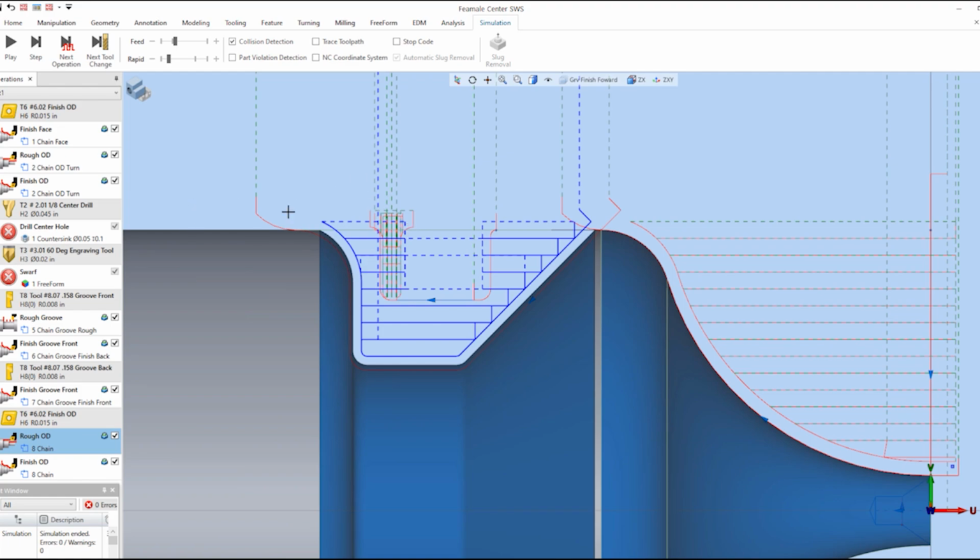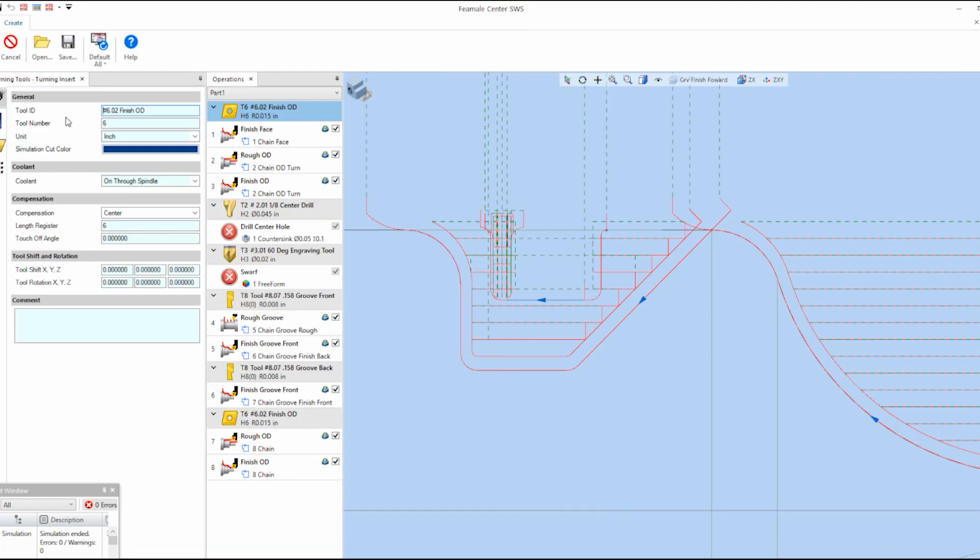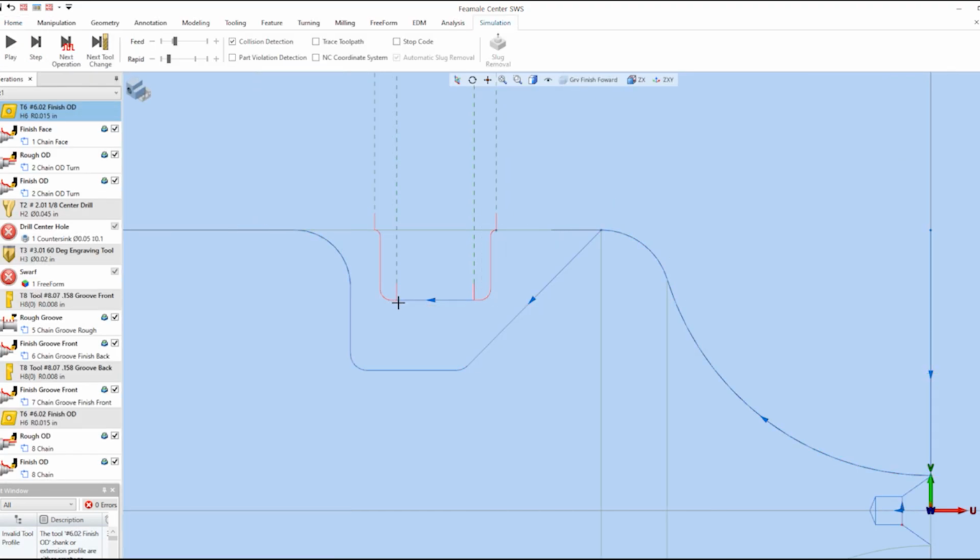So anyway, I just want to show you the difference in selecting different tip directions in your CAM software. And like I said, this needs to coincide with the way you actually set the machine up. Or if you're programming for somebody but not running the machine, you need to tell them this is the way you did it, because they could make a mistake and screw up the first part if they didn't know this. This is the normal one I use as a corner for most everything.